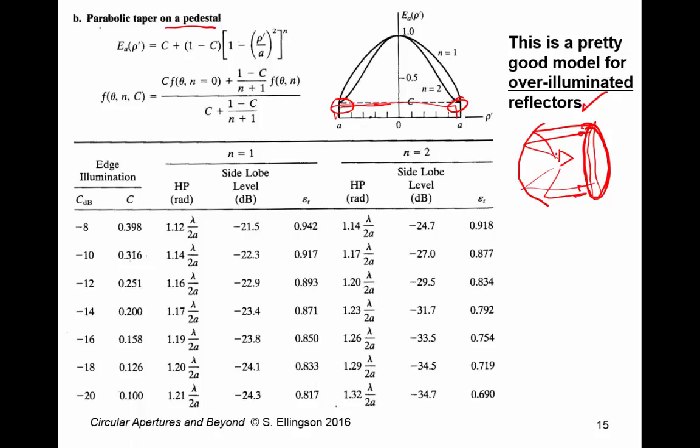And we also know that the way this feed works, it doesn't just stop at the edges. It throws some energy beyond the edges. It spills over. So we know that the equivalent currents in this aperture don't go to 0 along here. There's some non-zero value. So this thing is actually representing a realistic reflector which is experiencing some spillover. The spillover is represented by the non-zero values here.